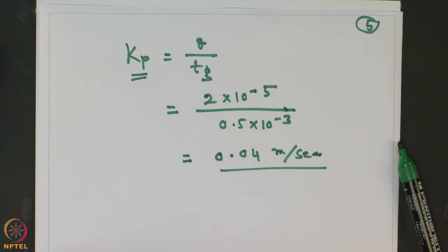One is filtration, where you use the term permittivity of the geosynthetic material when the water flows across the plane of the geosynthetic material. You can determine theta p, and the unit is per second. In case of transmittivity, the water flows along the plane of the geosynthetic material, and you can determine the transmittivity of the geosynthetic material. The unit of transmittivity is meter per second.